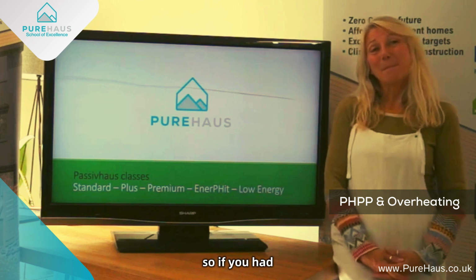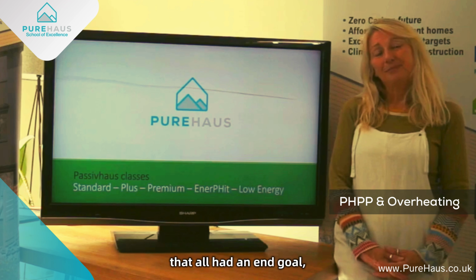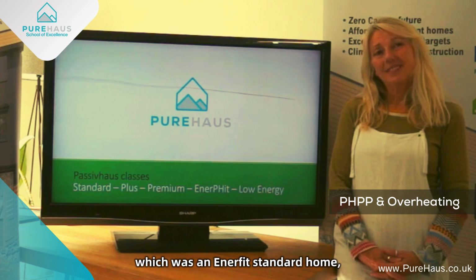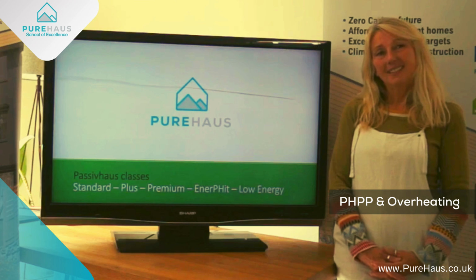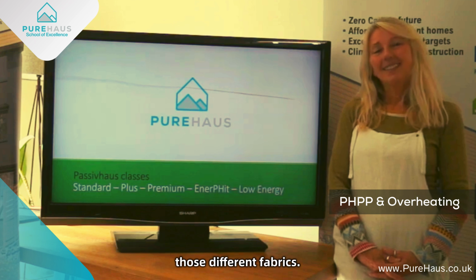Yeah, so if you had 8 different wall types that all had an end goal of being consistent to achieve the outcome that you wanted, which was an EnerPHit standard home, you would have had to implement different levels of thickness, different types of insulation, and also consider how those different types of insulation connect and work in harmony with those different fabrics.